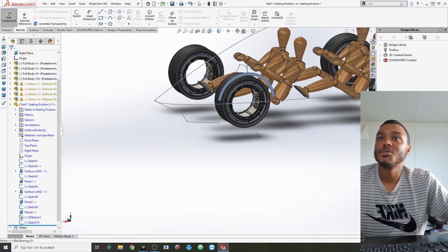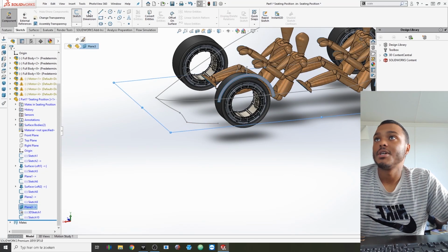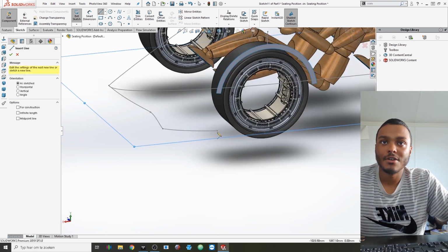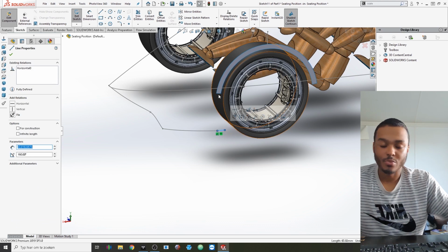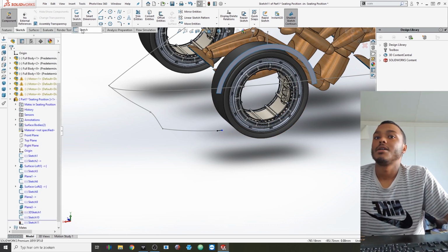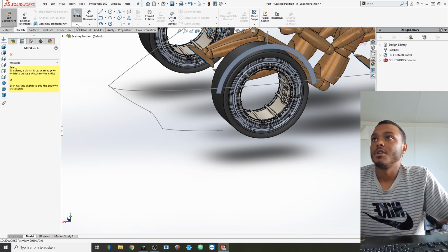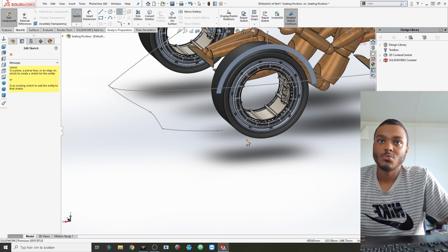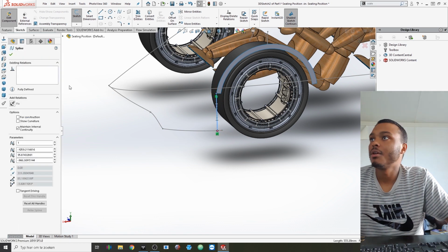So now we have also surface here, so we can again click on that plane 3, use sketch, and again use like a 40mm line here that we can then attach to this point. So it's now 63, select 40, and I can just close that sketch down, and again use 3D sketches, put the spline tool up there again, and I can just draw one line here.